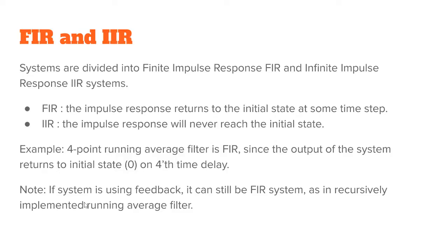Based on the impulse response, we can divide these systems into two categories. One is the finite impulse response systems, meaning simply that our output has an ending. If you feed in an impulse function, does the impulse response go to zero after some point and stay zero? Then our impulse response is finite.